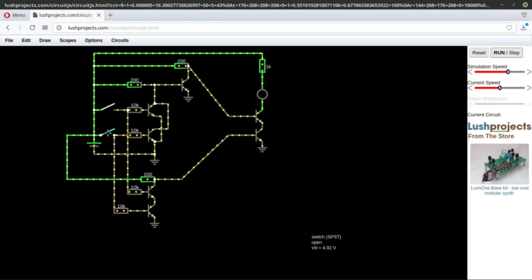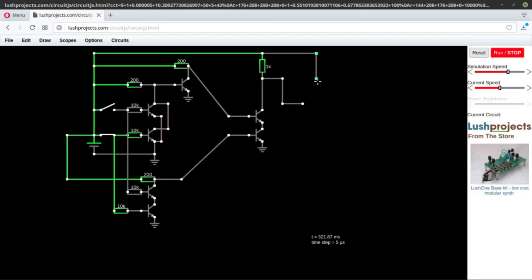Again you have a small problem here. This one is within the circuit. We need something outside the circuit. So you have to take this output and feed it to a transistor through a resistance of 200 ohm.